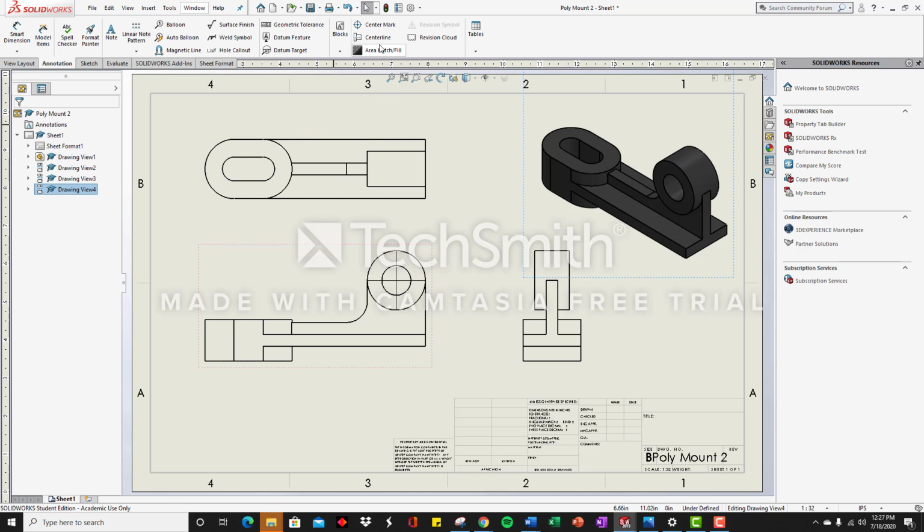So the reason why we have center lines, it's a point of reference so we can do our dimensions. Center lines and center mark lines are important for circles, finding obviously the center of the part. So this is how we do that.